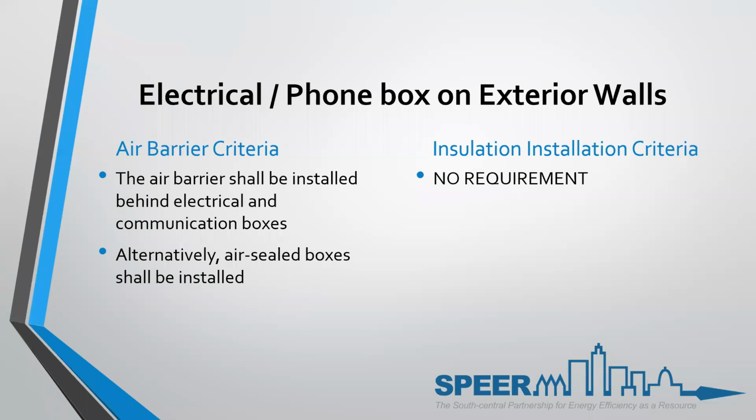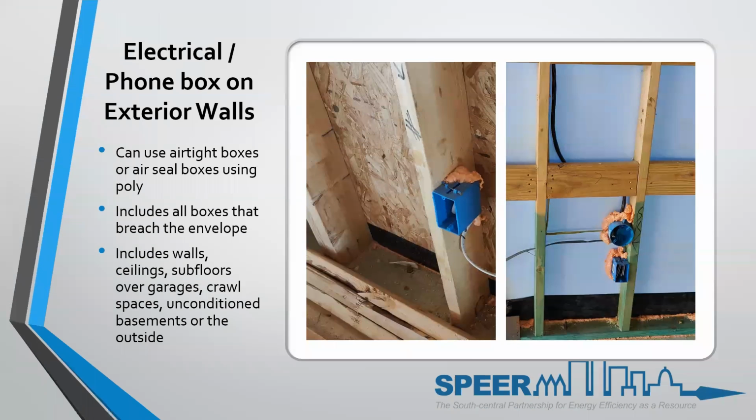There is no specific requirement yet, even though a water heater and or an AV box is taking up the majority of a 3.5-inch cavity. When you go to 2024, someone is trying to rewrite that section of the code to say that it still needs to have insulation between the conditioned and unconditioned space. So you may have to fur out those places to actually still have insulation. It can't be just a big 2x4 section that's uninsulated and allows for heat transfer into the home. So not yet is there a requirement for insulation, but it's coming.